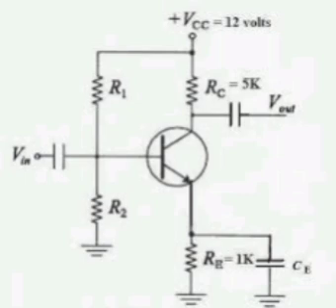volts. Now normally with the 250 volts, taking the same diagram, the current through the 250 volt source is I equal to 250 by 5 plus (250 minus 20) by 25, that equal to I equal to 59.2 amperes. Power supplied by 250 volts is 250 into 59.2, that equal 14,800 watts, that equal 14.8 kilowatts.